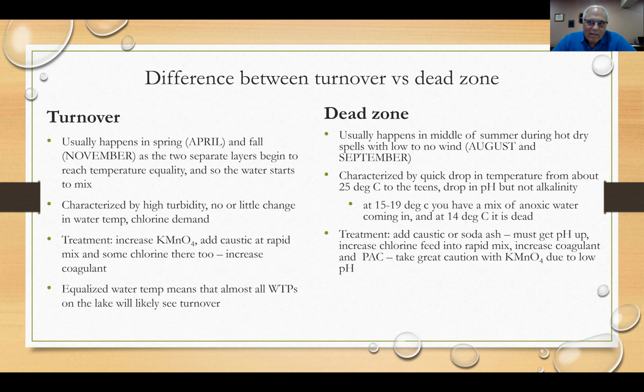That's fine. But remember that permanganate is a very weak oxidant when compared to chlorine. Now, I know you don't want to put chlorine on because of the trihalomethane issues, and I respect that. The chlorine will oxidize manganese much more quickly, much more readily than the permanganate does. And when you add potassium permanganate, you're adding more manganese to the water.